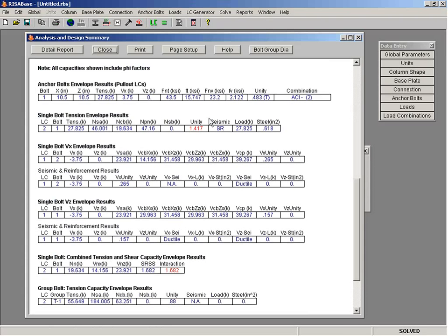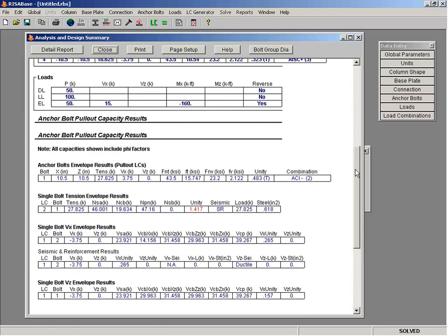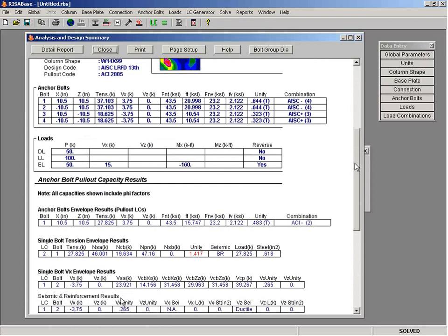Well, increasing the depth of the anchor bolts is one thing that I typically always think of, but of course, when we take a look at this situation where we're going to have a group failure and they're all going to pull out at once, it doesn't really matter how deep it is if the entire group is just going to yank out in one shot. So instead of doing that, maybe what we need to do is just spread the load out amongst more bolts.